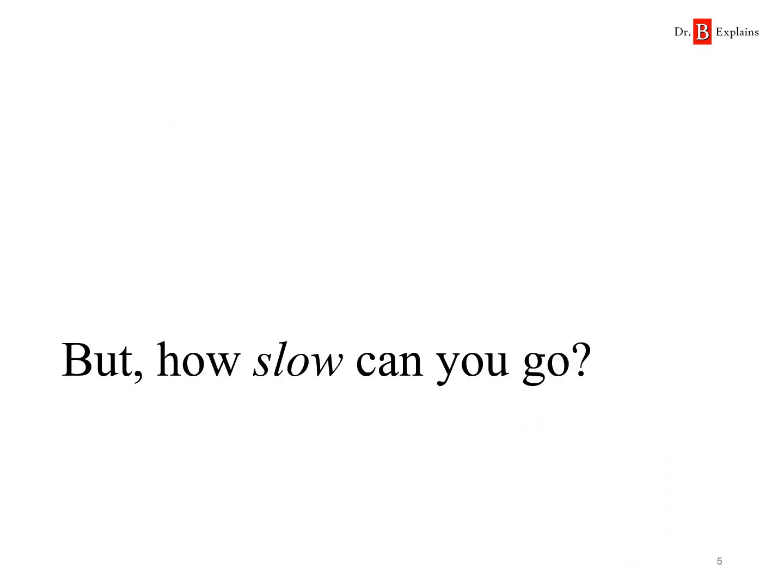So of course, we're talking about impact. It's dynamic loading. We talked about the statics, and we said, look, if it's instantaneous, it's the most severe. If it's gradual, then it's the less severe. And so the question should be, like, how slow can you go so that it's not static, but it's actually considered now a dynamic or an impact load.